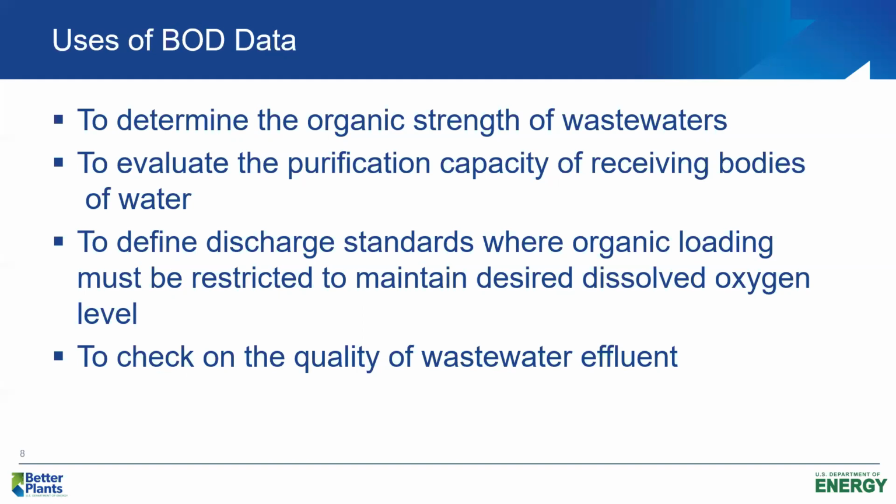And then the ultimate amount, or 100% of the BOD, will usually be exerted in about, again, 25 to 30 days. But we'll use BOD again to evaluate what happens in the receiving stream when we discharge an organic wastewater. Bacteria in the stream break down the organic matter, consume oxygen, and we're concerned about protecting the dissolved oxygen levels in the stream to support fish and other aquatic life.